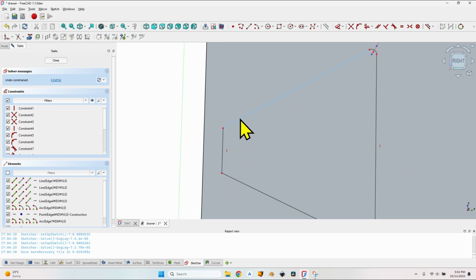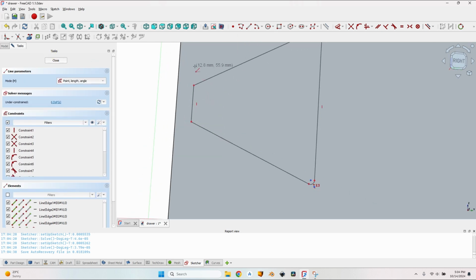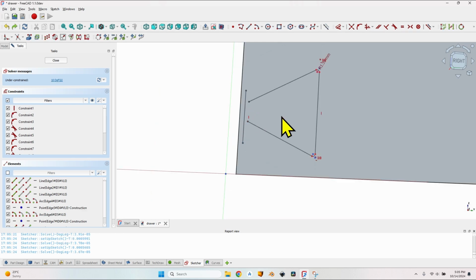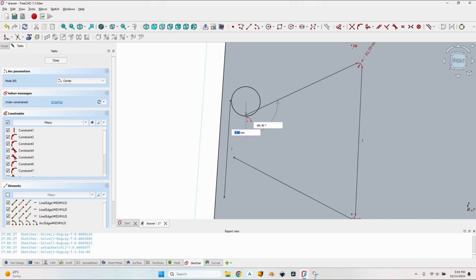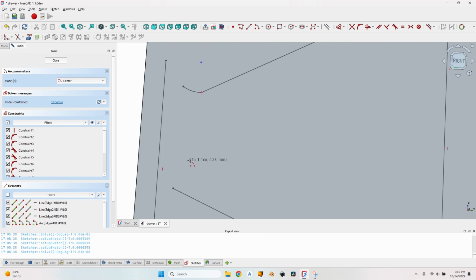That is because the roundover should be this way, should be to the outside, so when milling matching dovetails I can mill them. If I mill the roundover to the inside, it will be impossible to mill them on the corresponding piece. So how do we do that? First, let's create a new line here, place it random, set it vertical, and now let's delete this line from the first drawing. Let's create some arcs, select the center, select this point and create a random arc.